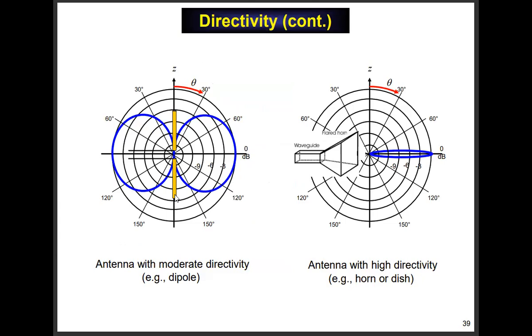And the impedance then is about 73 ohms, most commonly fed with a twin lead. In fact, like I mentioned the other day, you can think of a twin lead just unfolded like that to make the dipole, right? So it's a natural thing to feed it with a twin lead. Anyway, here's a pattern. I'm not going to claim it's drawn exactly 100% accurately to scale, but more or less what it looks like. Okay, so it's not particularly directive.